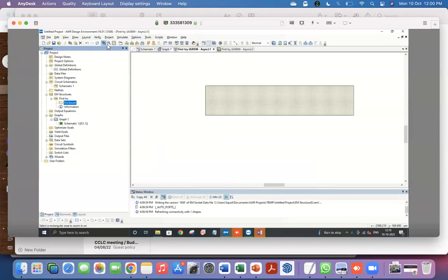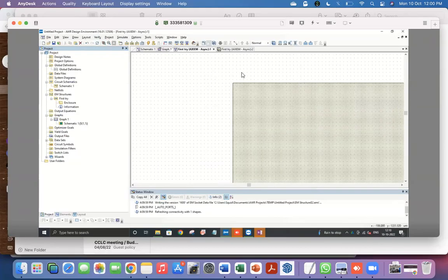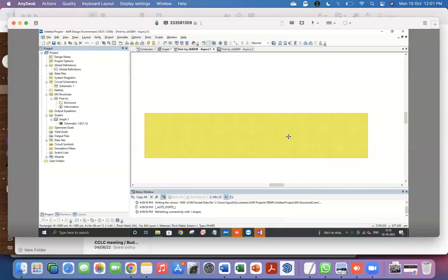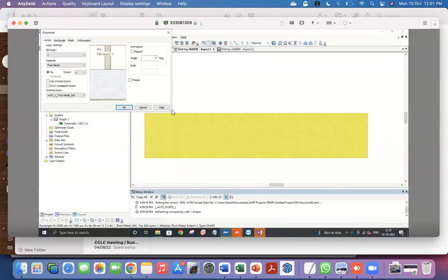But you basically can see that grid if you zoom in. So it's this grid spacing you're seeing, these dots, they are spaced 10 micron apart, which means if I try to drag and move this, it will move in these 10 micron units. I cannot do it as a finer step. So that's what that is for. Now, this metal which is at ground, we have to define what that metal is. So we right click it, put shape properties.